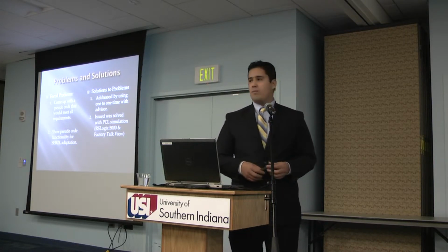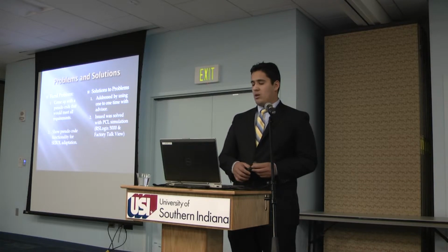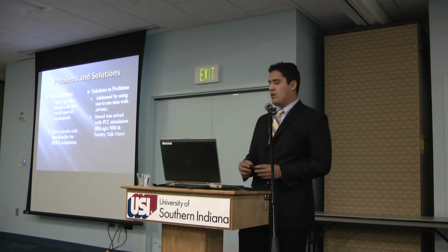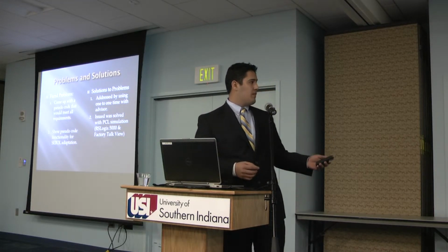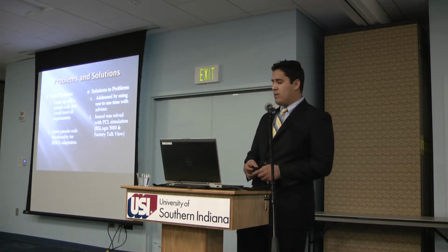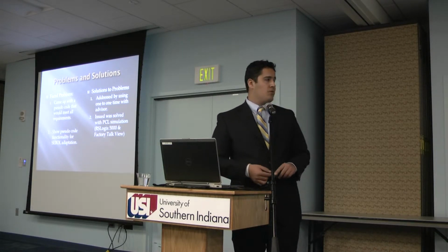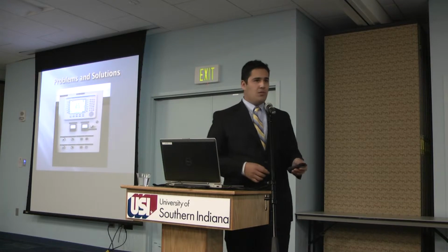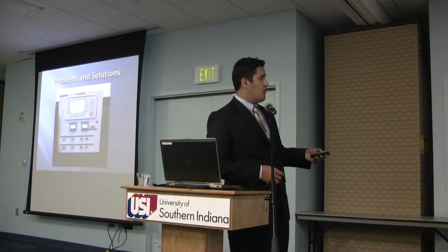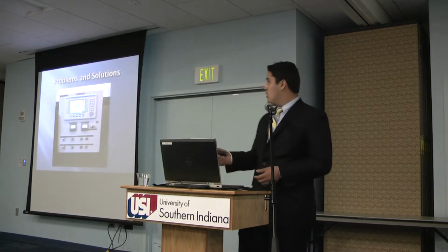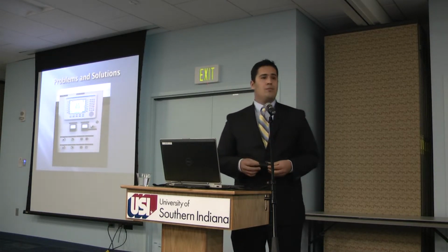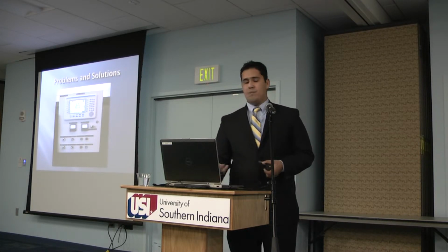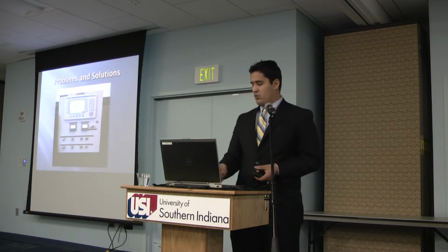For that, we solved the problem by creating a simulation through a PLC simulation with two programs, RSLogix 5000 and FactoryTalk View. RSLogix 5000 was used for the ladder logic, which I'll talk about a little later, and FactoryTalk View was used to create the HMI, human machine interface. This is the box that I used to recreate the program. These boxes were given to me by the USI faculty, and with that I proved the functionality of the pseudocode.